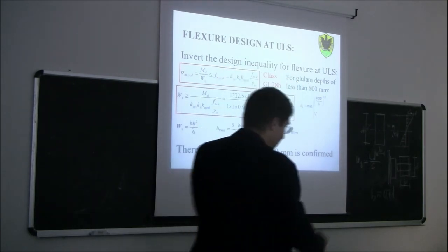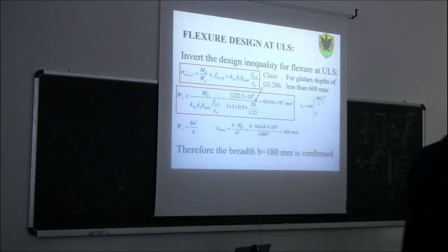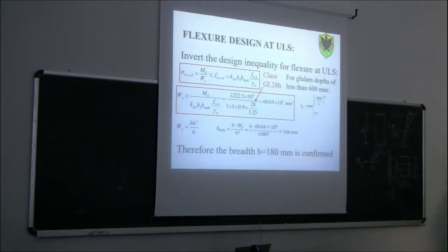So, also the other criteria, if you remember, is that the breadth cannot be 166 millimeters. Nor can it be 170 millimeters, because I told you that the breadth changes in steps of 2 centimeters, so there is not a continuous variation. The breadth must be either 160 or 180. Since we got 166, the only possibility is 180.